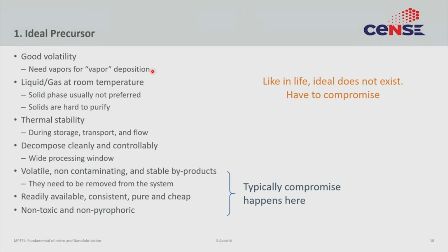It must be thermally stable. You want your precursor to do the chemical reaction you want only inside the chamber, not in the tank where it is stored, not in the gas lines where it is being transported, and not in the pump where the byproducts will go.